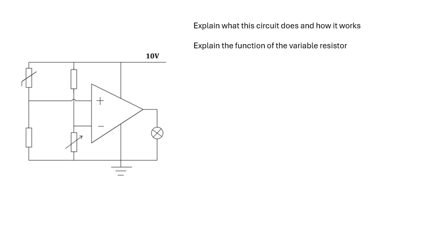So, V ref is there. Yes, and again, you've got a potential divider which will determine what V ref is. Here, V in, you've got another potential divider. There's your other potential divider. And this resistor is a thermistor. So basically that resistance depends on temperature. If the temperature is big, then the resistance of the thermistor is small. So V in will get bigger.